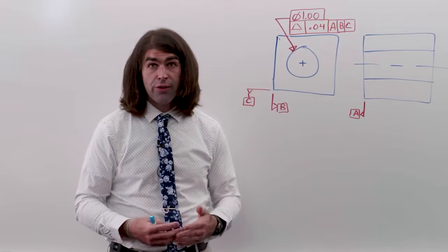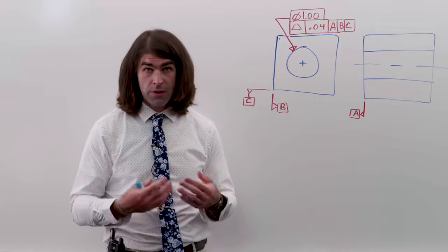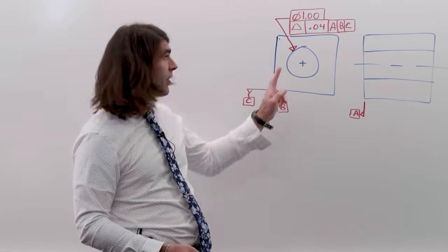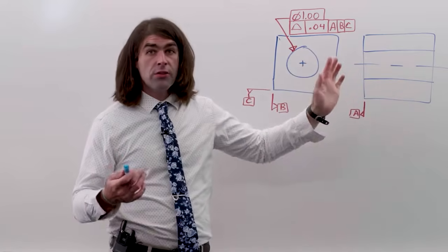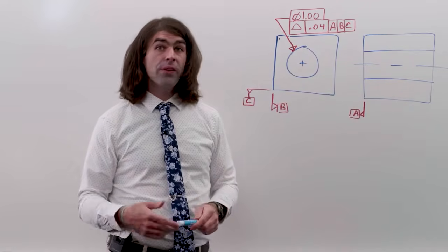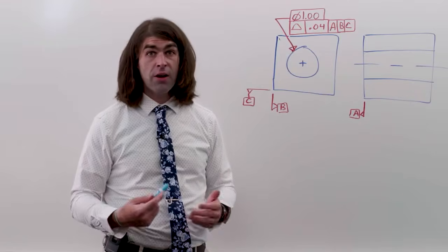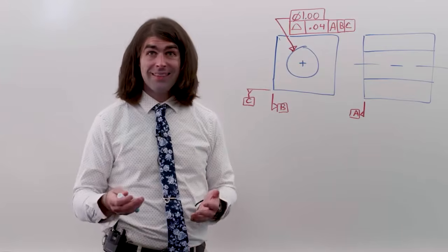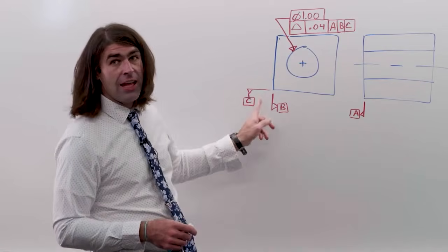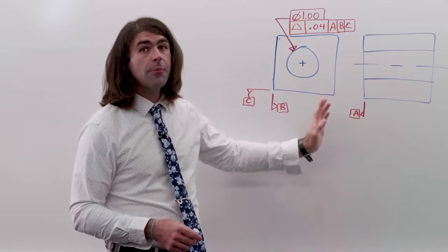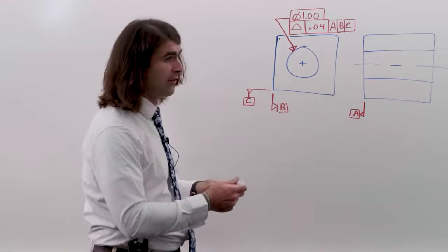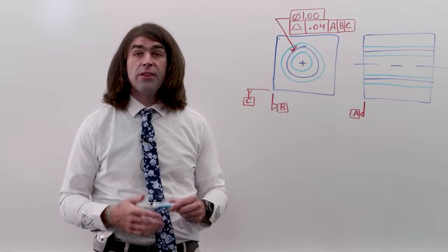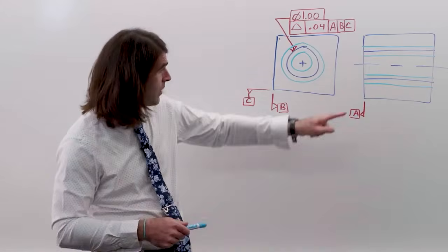We've got a profile of a surface applied to a hole. Now, of course, it's going to be a basic dimension in this case. We've got 3 datum features and 3 datum references. So what this gives us is a tolerance zone that follows the true profile of the hole. Since it's 3-dimensional, you essentially have 2 concentric cylinders that are located to A, B, and C. It's perpendicular to A and then located to B and C. So what that would look like is something like this. Okay, so you've got tolerance zones where the part has to fit within.